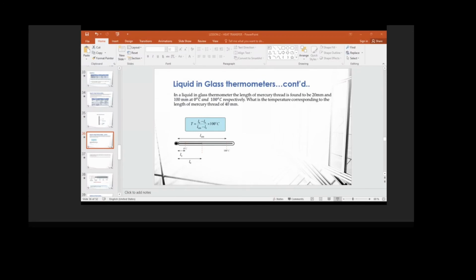All right, some disadvantages: they're expensive. Right, the fact that they can read that range in temperature, definitely expensive. The large bulb size compared to a thermocouple, the bulb part of it is very large. So this is not a very small thermometer. It requires a separate bridge circuit system, so it needs an external bridge circuit in order for it to work. It needs power, an external power source. Right? And there's self-heating caused by current flow, which can affect the accuracy of the instrument.